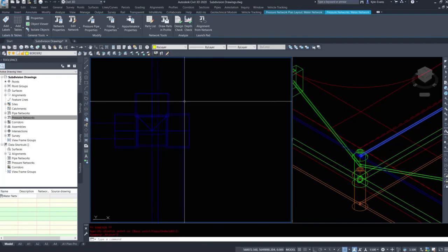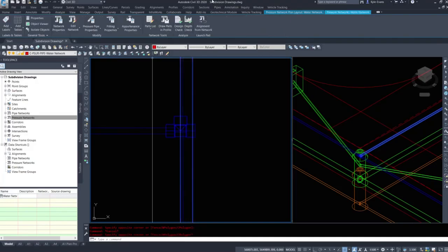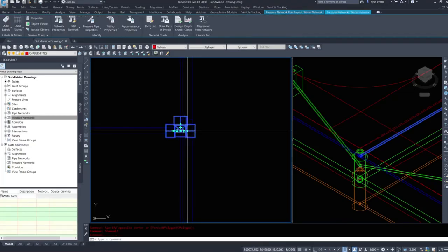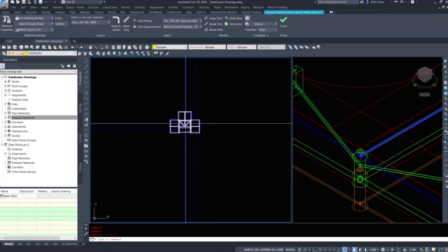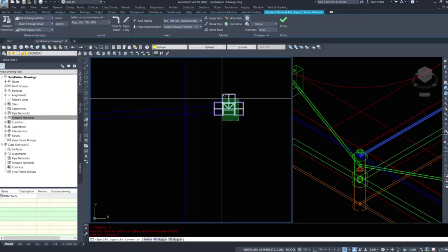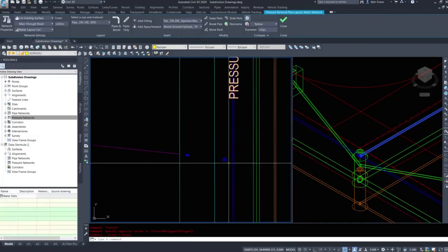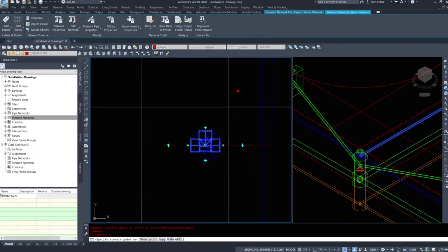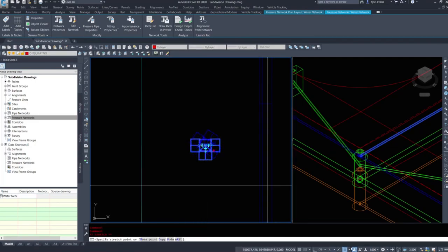So this is a little bit finicky. It doesn't actually break the pipes either. So in your ribbon, we can break the pipe, say right there. Rotate our T with these grips. There should be a little rotation one, but it doesn't. Oh, so that pipe is connected. We'll just erase that pipe. There's our rotation grip. And if you start clicking these, the rotation works backwards.